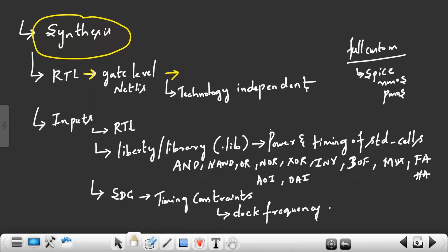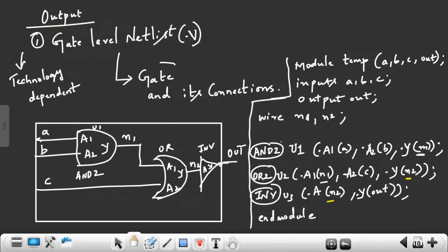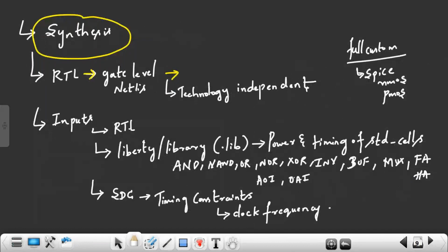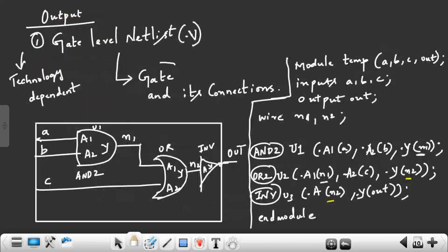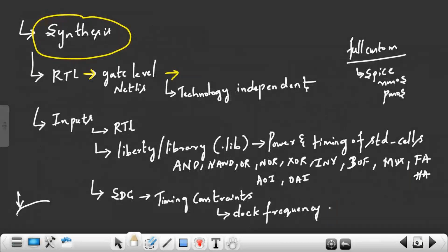Okay, assume that the netlist I have and the .lib I have for 14 nanometer have the same names: cell name remains the same, pin name remains the same. But at 7 nanometer I will get less leakage power. Overall design power will be what? Less. I will get fewer violations. If I use the same netlist for 4 nanometer, I may get more power because my synthesis tool has not done optimization for 4 nanometer. It has done only for what? 7 nanometer. So I'll get different power and different timing violations. So I cannot use that.